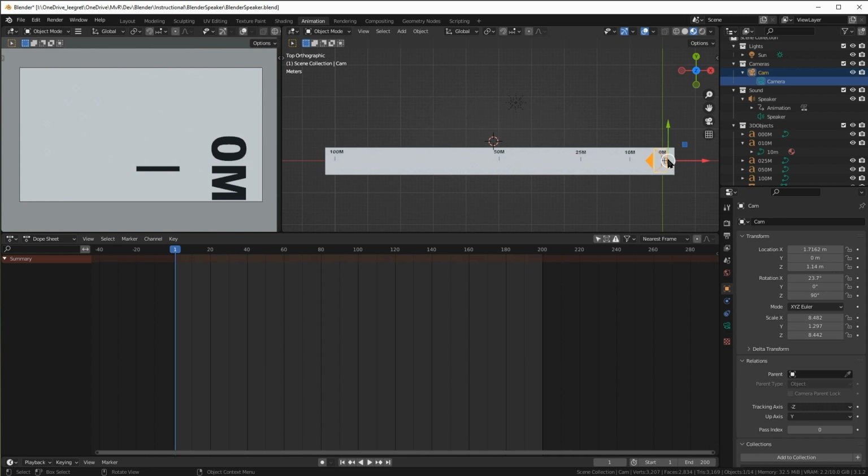We've got the camera in the start position. Yep, tick. We've got the frames in the start frame. Yep. So we've got the location correct and we've got the frame correct. What we need to do now is lock that position as a keyframe. The easiest way to do it with this is, just to the right of this property, location X, there's a padlock for locking it, which we don't want to do.